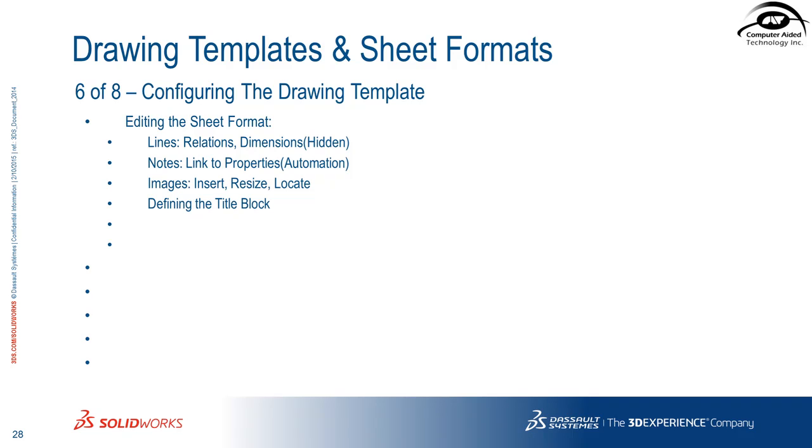There's been some stuff that's been added to the drawing templates over the last few years that maybe you're not utilizing, but you could. And maybe you're not because it's the way you've always done it, and it's been working, and you just do it the way you've always done it. One of the old school methods, for those of us who've been around more than a few years, a lot of times we would go, when we needed to add text to a title block for a drawing that we're going to type in manually, we would go into edit sheet format.